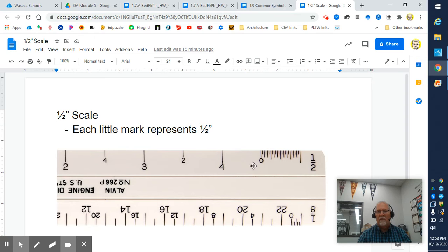If you can think back to our video when we worked with the architect's scale, this is basically 1 foot broken down, or we kind of zoomed in on this portion where we have to figure out what all these little marks mean. The easiest way I always remember this is looking at this. If this is 0 and this is 1 foot right here, right in the middle is 6 inches. 1/2 of 6 inches is 3 inches. Then we have 3, there is 2, there's 1, and there's 0. That means every little line is a 1/2 inch.